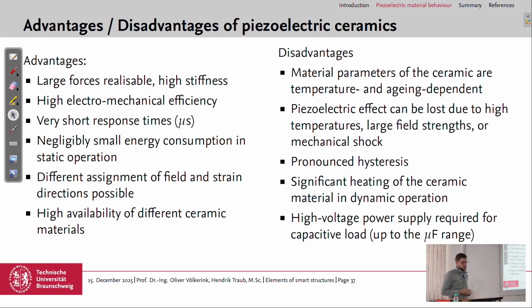And with this, we come to advantages and disadvantages of the piezoelectric ceramics. So we have large forces we can achieve. We have a comparably high stiffness. We have a high efficiency of the material and also very short response times. So we can use it for dynamic applications. In static operations, we have very small energy consumption.